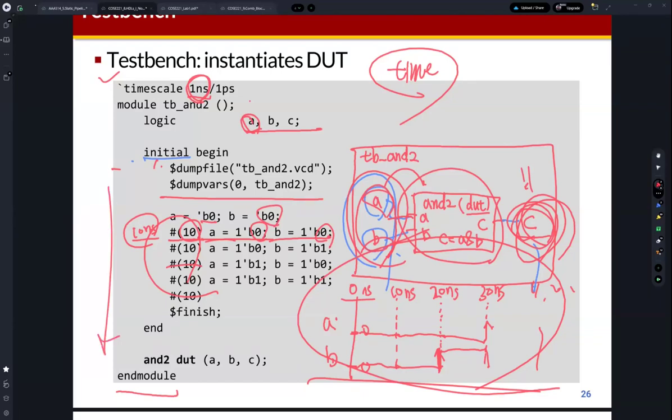But you need to remember that, to verify and check the correctness of our design, which is called the design under test, we also need to implement a Testbench module. The Testbench module includes the input signals changed by time. Input signals are given to our design under test, then output signals will be generated, right?